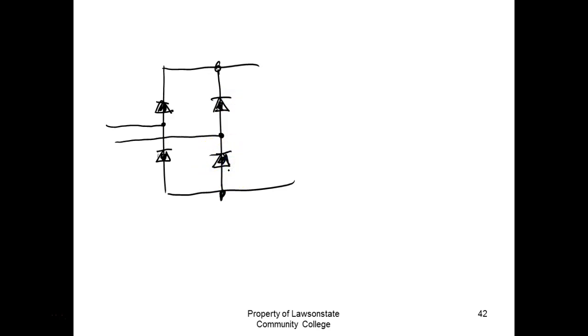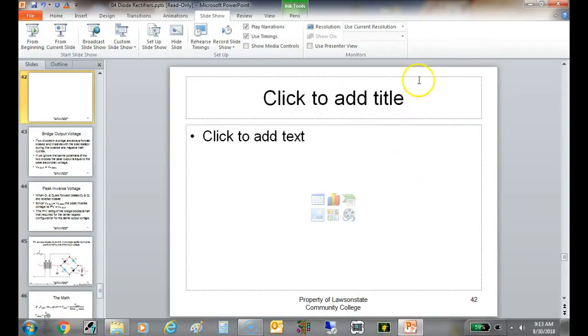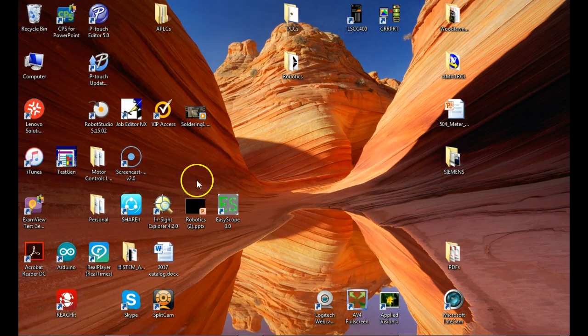And then we're going to bring our AC in. And if I wanted a negative power supply, I just do what? To the diodes, I just flip them around. Everybody okay? That makes sense? So it's a lot easier to wire up if you understand that. So we got our train over here. So first of all, I need 4 diodes.